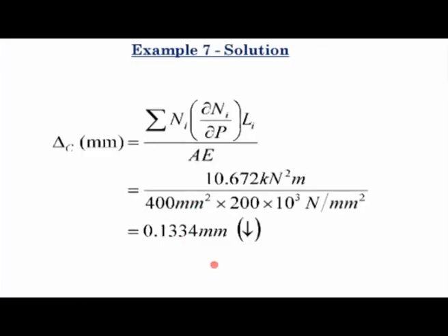In the deflection formula, we are getting units of Newton meters, but in the slide they showed millimeters. If you are referring to slide number 63 that I am showing now, yes, this has kilonewton square meter and this has Newton per millimeter square. So it gives you Newton millimeter as you have mentioned. But remember, on this side there is a unit load of 1 Newton.